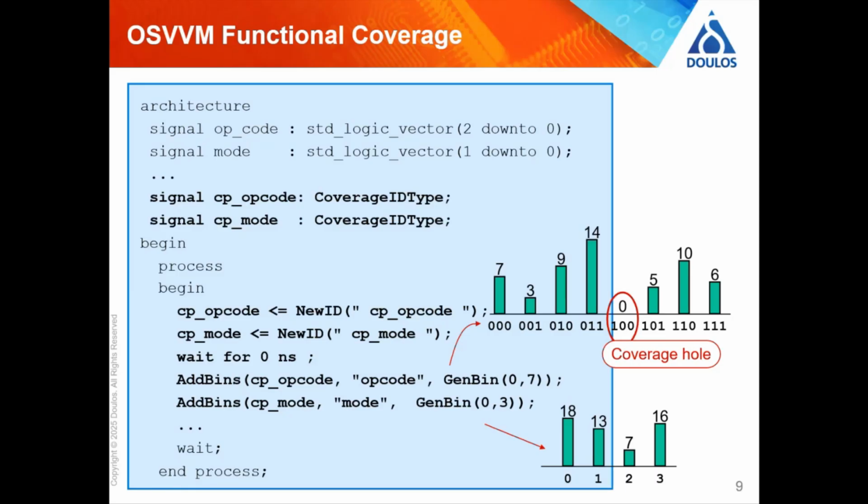Protected types are the natural way to do this in VHDL in some ways, because they're a nice interface. And for those of us who actually did some object-oriented programming once, that's quite a nice way to work. But the trouble is, in the VHDL language, you can't pass them around, for example. You can't use them as arguments to functions or ports on entities and things like that. You have to just have these shared variable things, which immediately means global variables, and my alarm bells are ringing saying dodgy, dodgy. So the way that we use them is unfortunately a bit restricted. Although they're a nice idea, the VHDL language itself has some restrictions on how you can use them.